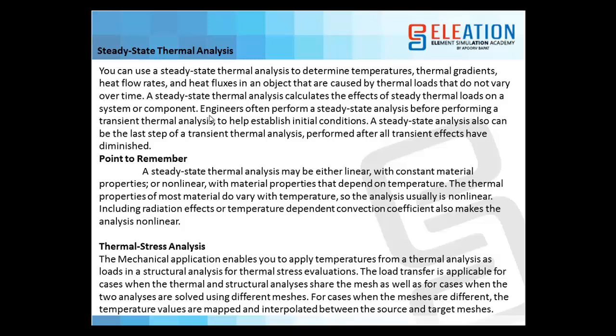So you can use a steady state thermal analysis to determine temperature, thermal gradient, heat flow rate, and heat flux in an object that are caused by thermal loads that do not vary over time. A steady state thermal analysis calculates the effect of steady thermal load on a system or component. Engineers often perform a steady state analysis before performing a transient analysis.